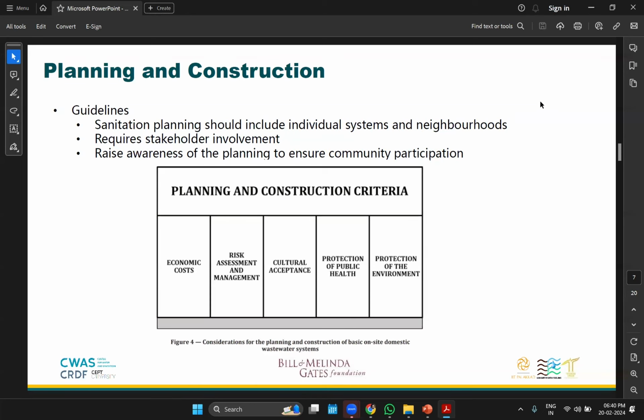In terms of protection of the public health, we're looking for potential backup of systems, potentially exposed populations, and contamination of the land. In terms of protecting the environment, we are evaluating within the guidelines surface breakthrough from potential structural failure, location of residents and water wells, and the topography, for example, slopes and soils that may create effluent plumes. Next slide, please.